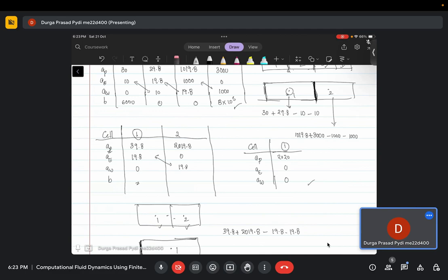I have a basic question on SIMPLE. Can you take that? So is it on the method, right? You know this momentum equation, a_e u_e star equals sigma a_nb u_nb star plus b_e, I'm just looking at the east face.